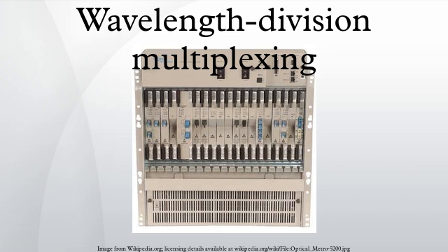EDFAs therefore allow a single-channel optical link to be upgraded in bit rate by replacing only equipment at the ends of the link, while retaining the existing EDFA or series of EDFAs through a long-haul route. Furthermore, single wavelength links using EDFAs can similarly be upgraded to WDM links at reasonable cost. The EDFA's cost is thus leveraged across as many channels as can be multiplexed in the 1550 nm band.